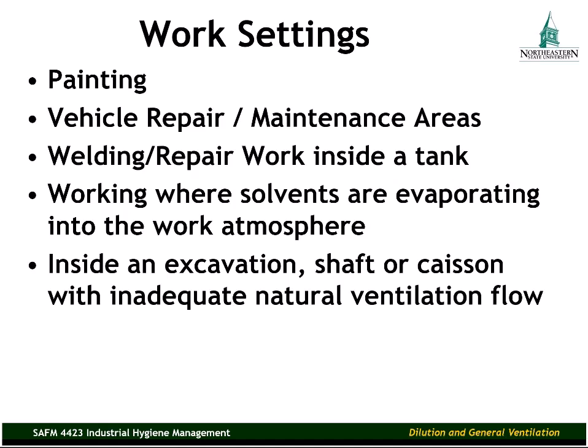But if you're inside of a tank, a shaft, a caisson, an excavation where the air can't move, that's where you may need to use dilution ventilation. If you've got something inside the excavation, shaft or caisson that is generating a high volume of contaminant, then you may need to use local exhaust ventilation to suck that contaminant out of there.